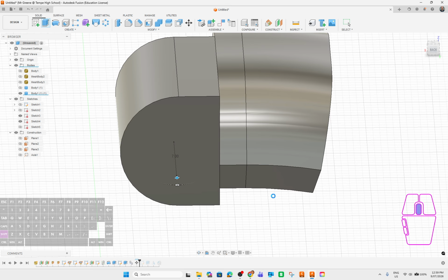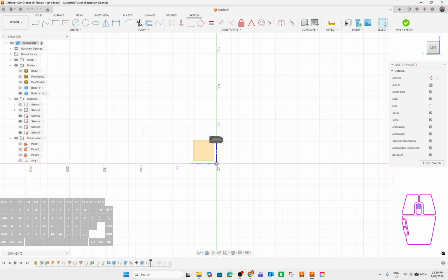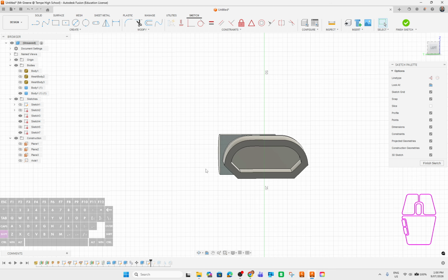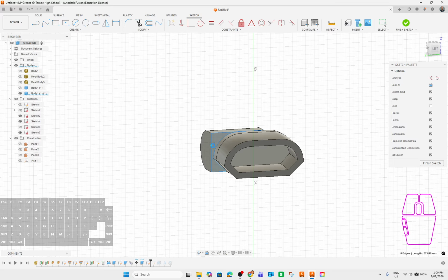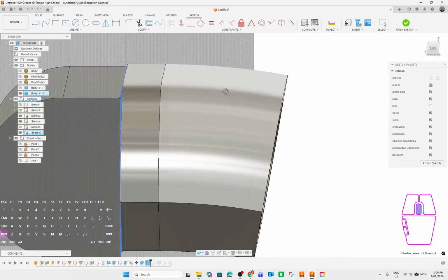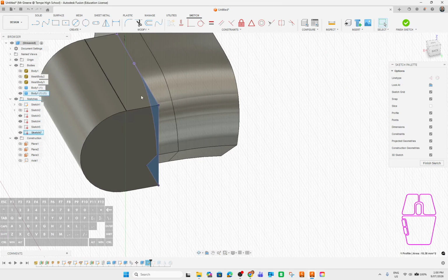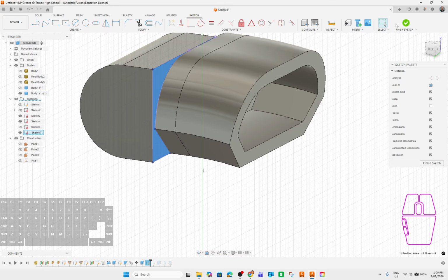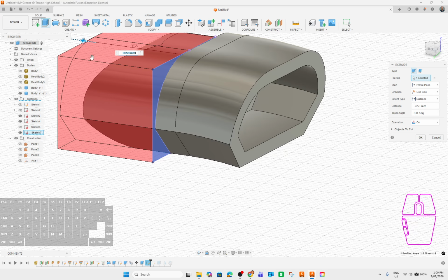And then do another sketch onto here, so go add sketch, and then I'll just project this geometry. So P here, and here, and here, and here, and here. So now I've got this section. Okay, and then it looks a little bit funny, but that's okay. And then I'll just take this out. So I'll go finish sketch, extrude this out this way until it's all gone.